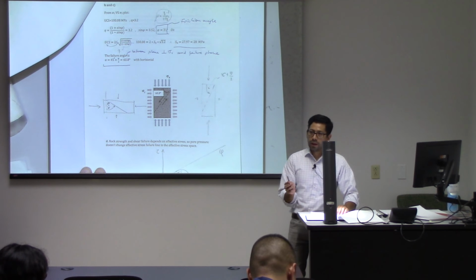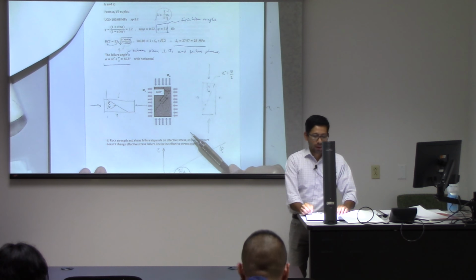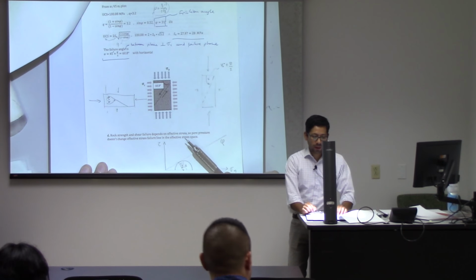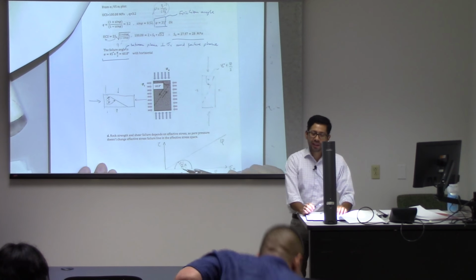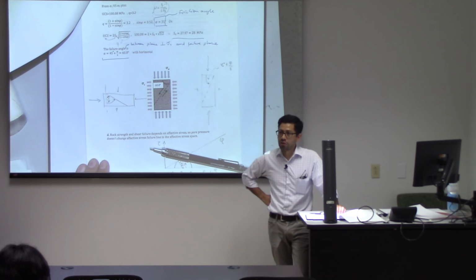Pore pressure. Pore pressure doesn't affect the shear strength of the rock. It just changes the effective stresses.